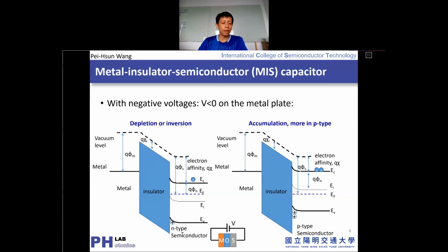So that gives you a general hint if you want to operate the band structure of the metal oxide semiconductor connection, what is the positive and the negative charge you should use under this constant. And also, as we previously mentioned, it still assumes the work function between metal and the semiconductor are perfect. So under the schemes, you can consider that the difference between the Fermi level between metal and the semiconductors will be exactly the same with the voltage we applied under the metal oxide semiconductor scheme, or MIS scheme.